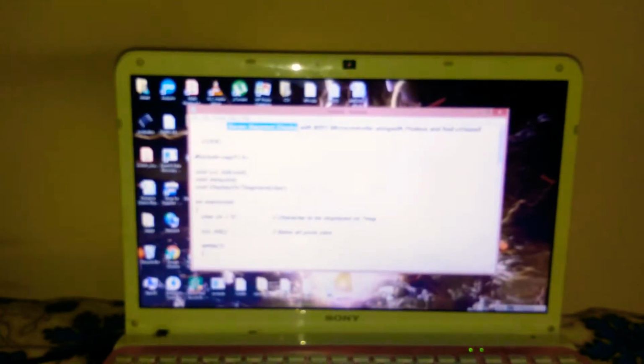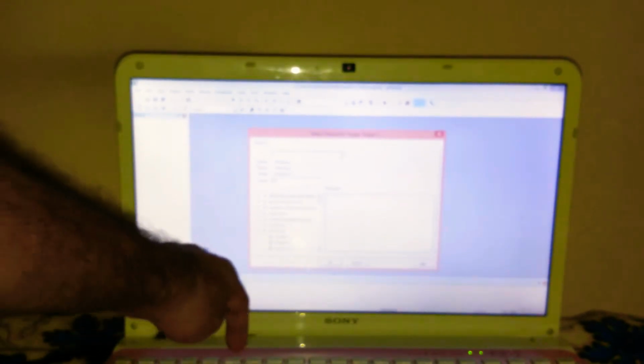We all know how to start this. First of all, open Keil uVision5. I will go to Project, New uVision Project. It's opening right here. I'm going to save this, and I'm going to name it SSD, that is, 7-segment display, and save it. Alright, so we have got this. Now just type AT89C51, because we are using the 8051.